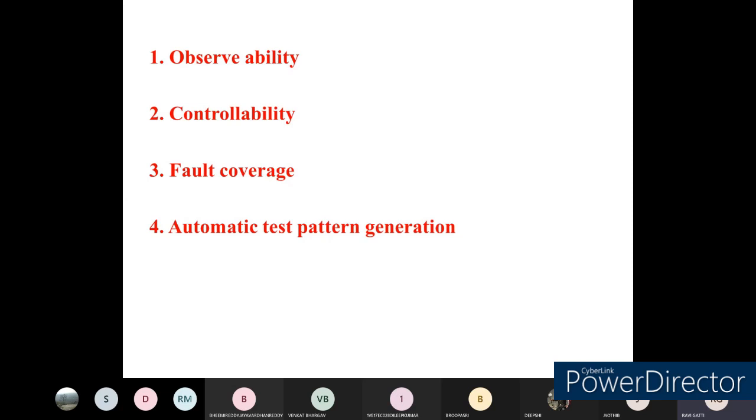Okay, and this process will be repeated for setting the node either to stuck at 1 or stuck at 0. In turn, every node stuck at 1 or stuck at 0 will be sequentially faulted. The fault coverage of a set of test vectors is the percentage of total nodes that can be detected as faulty when the vectors are applied.